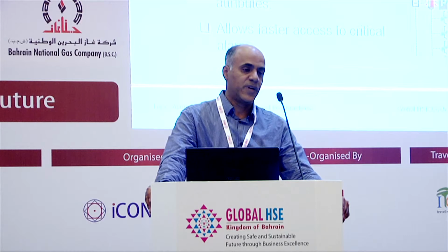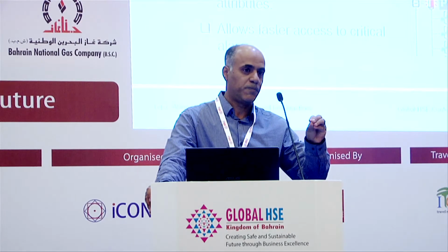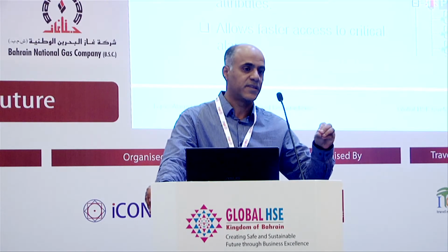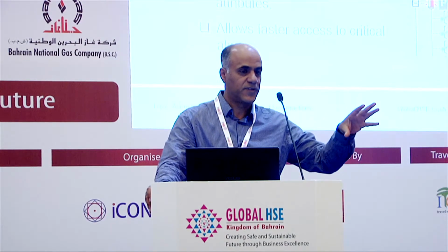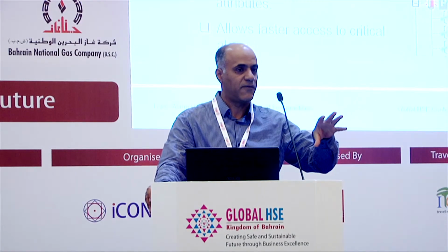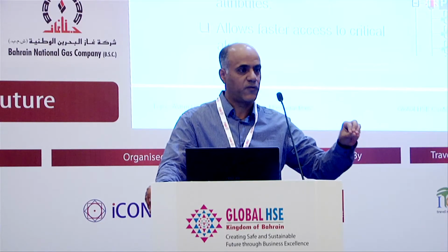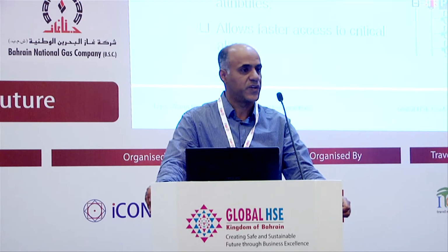That is, the operator will have the facility to remove an alarm which is not related to the disturbance to the process now or is of a lower variety, and it can be attended to later. Put it on a shelf, and normally shelves come in different categories, like you may have a one-shot shelf or a continuous shelf based on the conditions you set, and this allows faster access to the critical alarms.